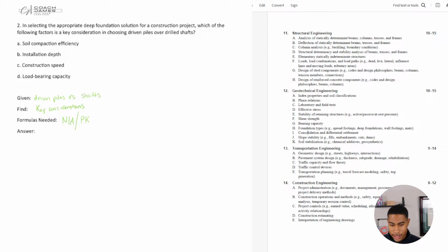What I saw was a steel pile, but there are different types of piles. You have timber piles, concrete piles, and steel piles. The specific type you select is based on the load requirements and your soil conditions. Driven piles can be a cost effective solution for certain projects, especially when the soil conditions are favorable for driving, right?